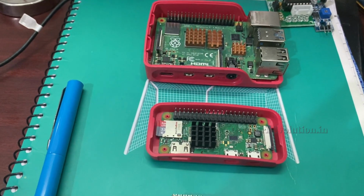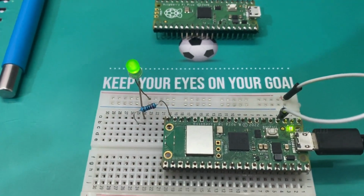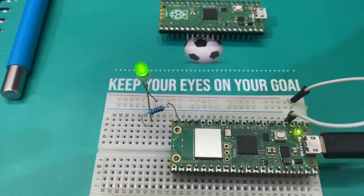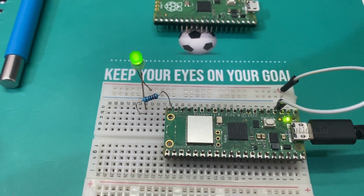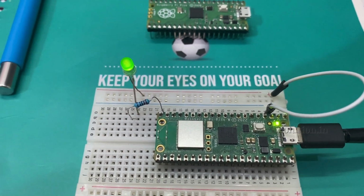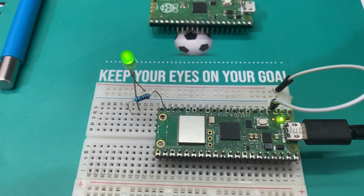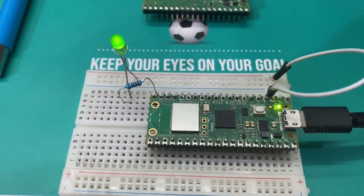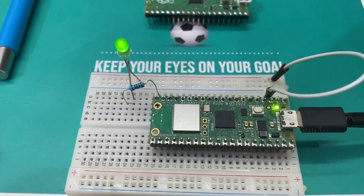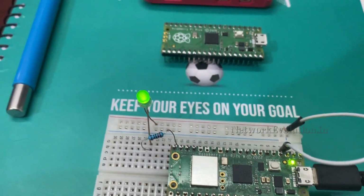Before we start coding, I'll walk you through some of the Raspberry Pi boards which I am having. This is Pico W. This is having inbuilt Wi-Fi antenna, but this supports only 2.4 gigahertz. You need to remember that. This can even act as a soft access point which supports 4 clients. All those configs we will see later. This is having dual core ARM processor with 133 megahertz of clock speed and 2 MB of onboard flash memory. And there you can keep the Python files.